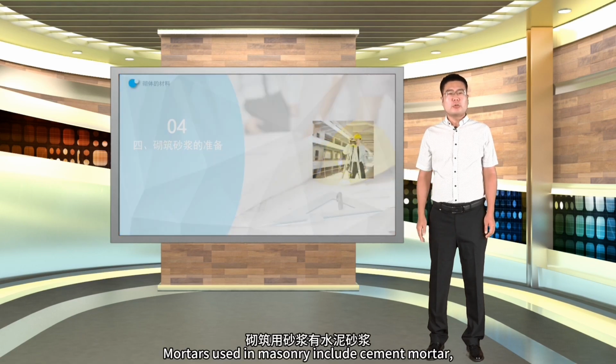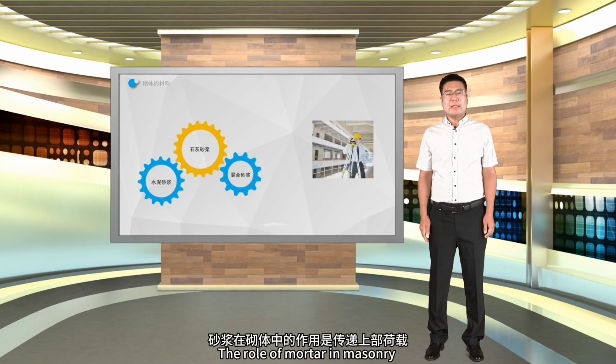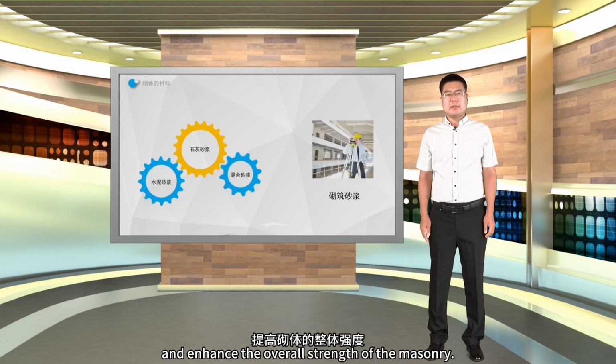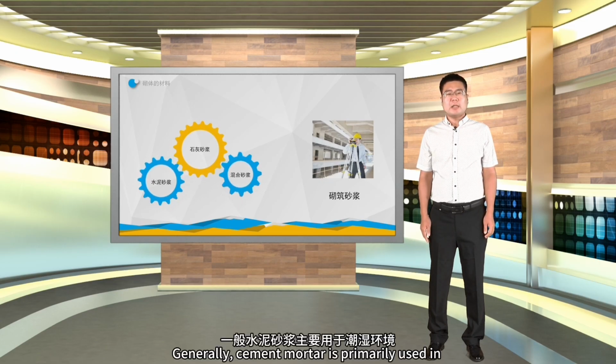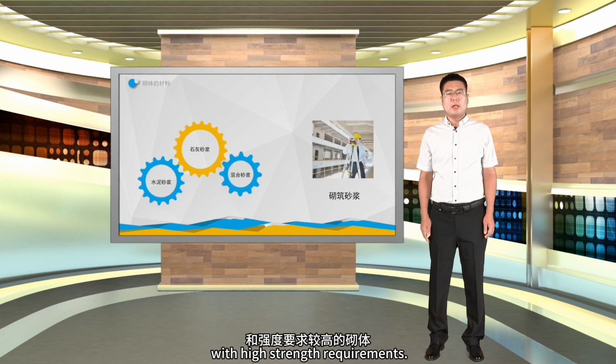Mortars used in masonry include cement mortar, lime mortar, and composite mortar. The role of mortar in masonry is to transfer superimposed loads, bond the masonry units together, and enhance the overall strength of the masonry. The selection of mortar type and the determination of its grade shall be based on design requirements.